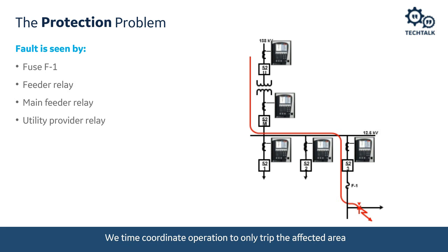So let's talk about some of the types of overcurrent protection. The simplest form of overcurrent protection is just an instantaneous overcurrent protection. And if we look at the evolution of overcurrent and even the evolution of protective relaying itself, this was probably the first type of overcurrent device or overcurrent relay that appeared on the scene. And this, in an electromechanical world, back 100 years ago or so, looked basically like a plunger relay. So it was a coil with a plunger in it.